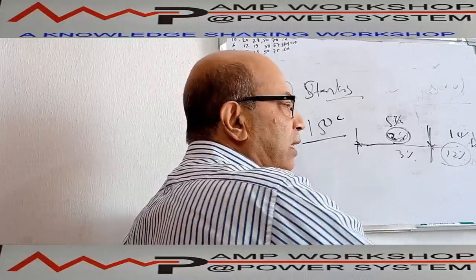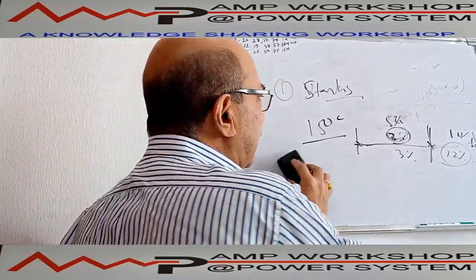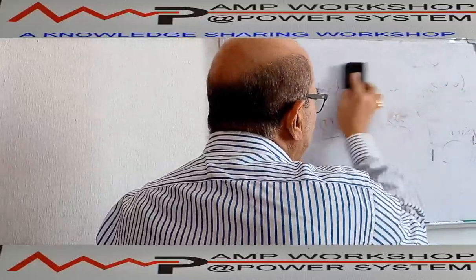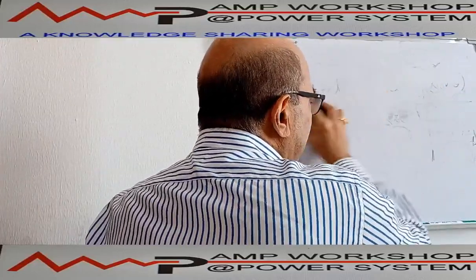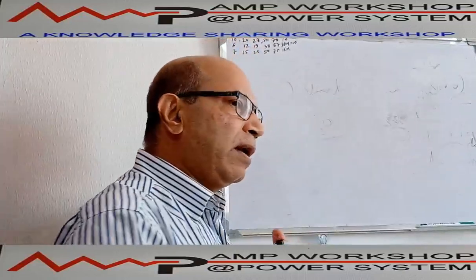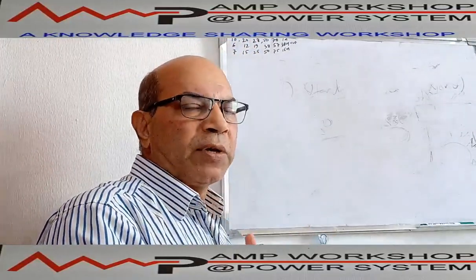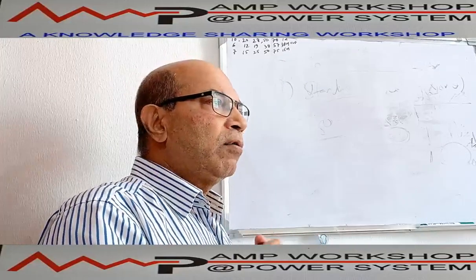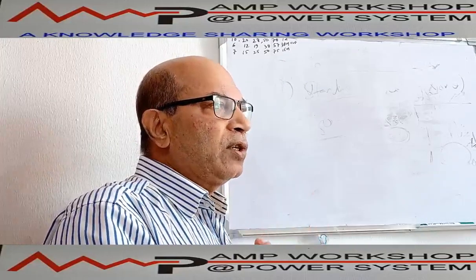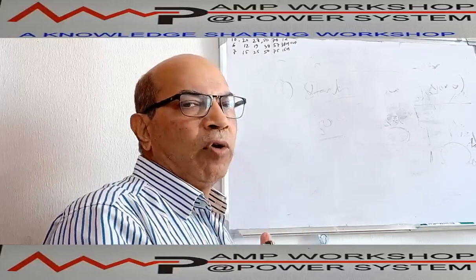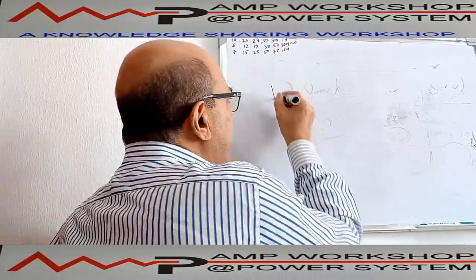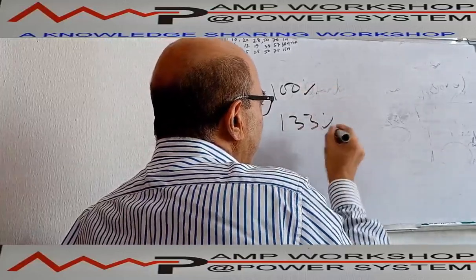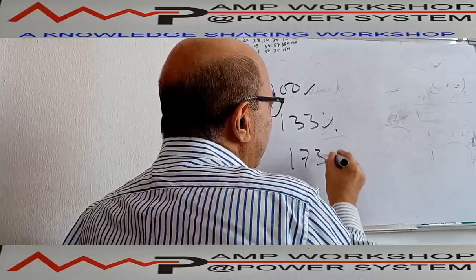So sizing is finalized. So this is the cable sizing calculation, cross section area sizing. Next part is that we have to select the proper voltage rating of the cable. Now the cable size is decided, and the continuous voltage rating of the cable is decided based on the grounding condition of the system. Based on the grounding condition of the system, there are 3 categories of voltage. One voltage category we call 100% voltage cable, another we call 133% voltage cable, and one is 173% voltage grade.